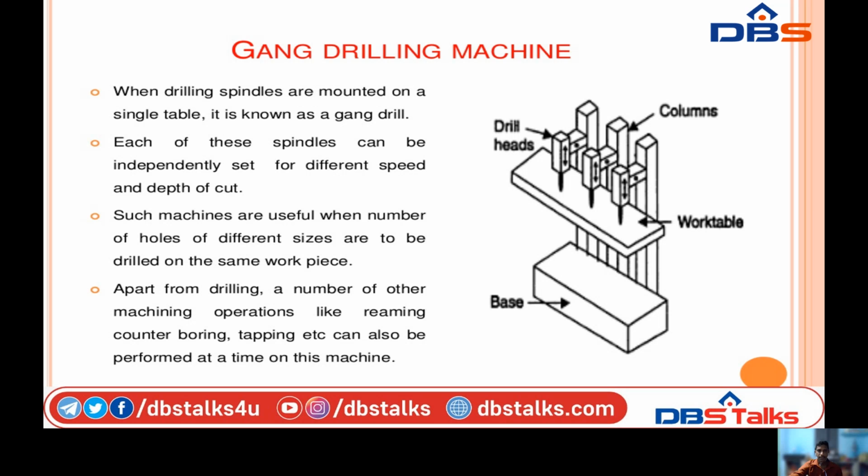Gang drilling machine. In a gang drilling machine, drill spindles are mounted on a single table. We are fixing all the drilling spindles on one table, and because of that we call it a gang drilling machine. Each of the spindles can be independently set, that means we set the spindles at different speeds and different depths of cut. Such machines are useful when a number of holes of different sizes are to be drilled on the same workpiece.